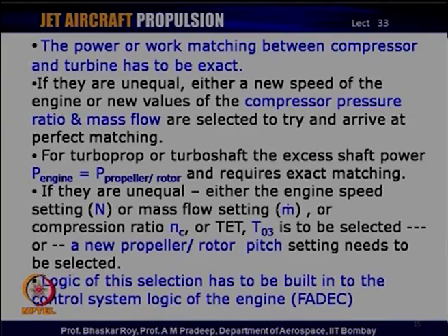Which means propeller and rotor should have a variable pitch mechanism available with it for selection of pitch depending on the power availability from the engine. And as we know, most of the propellers and rotors operational today do have variable pitch mechanism available with them.